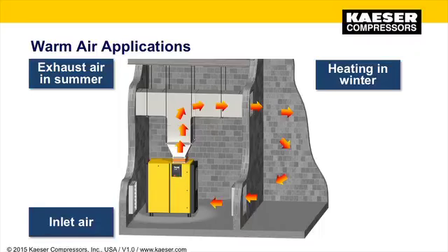Nearly all current compressor models have cabinets that channel the airflow through the compressor, and many designs exhaust the warm air out of the top of the unit, like the one shown here. This simplifies adapting compressors for space heating to simply installing the ducting and sometimes a supplemental fan to handle duct loading and eliminate back pressure on the compressor's cooling fan. Space heating can be regulated easily using thermostatically controlled motorized louver flaps for venting, thereby maintaining consistent room temperature by making continuous adjustments to the heating airflow. This is important to ensure comfort for people within working areas.